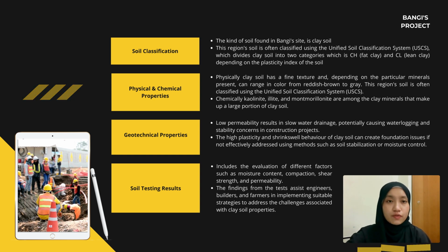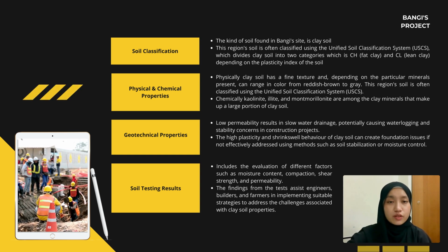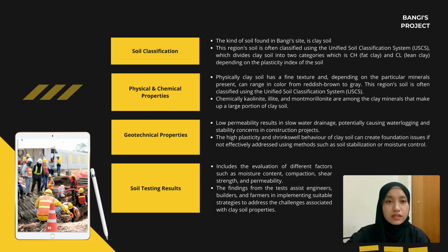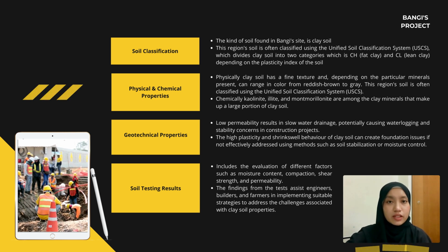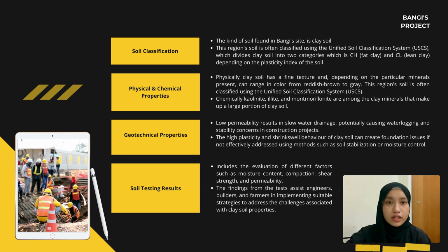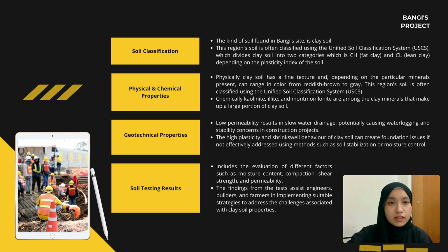The kind of soil found in Bani project is clay soil. This region's soil is often classified using the Unified Soil Classification System, which divides clay soil into two categories, which is CH clay and CL clay, depending on the plasticity index of the soil.